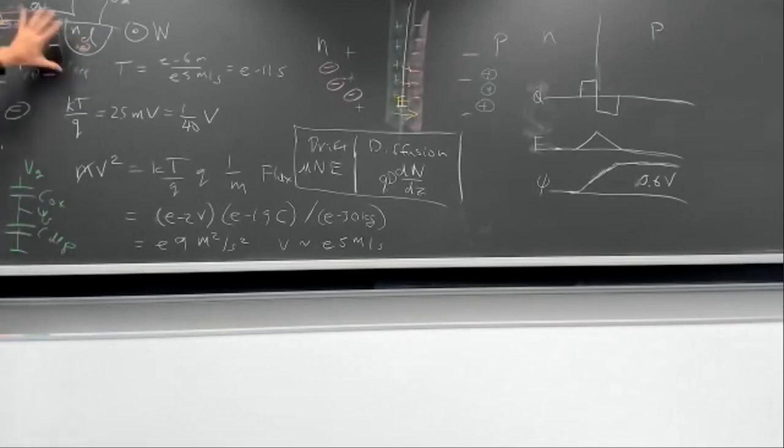If you just make a MOS capacitor and don't have an n+ source and drain, or you don't actually need the drain, right? You just need a source of electrons somewhere. If you don't have that, all you're going to get is a big depletion region at high frequency, right? It's just going to push away the holes and let them come back. But you won't get electrons.